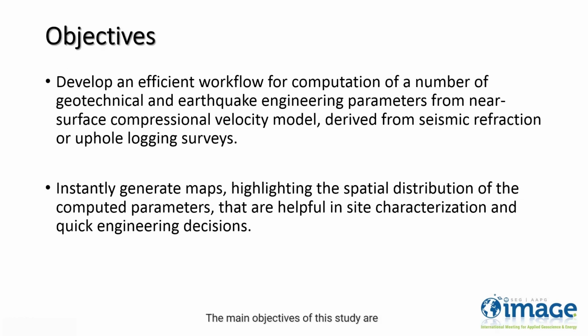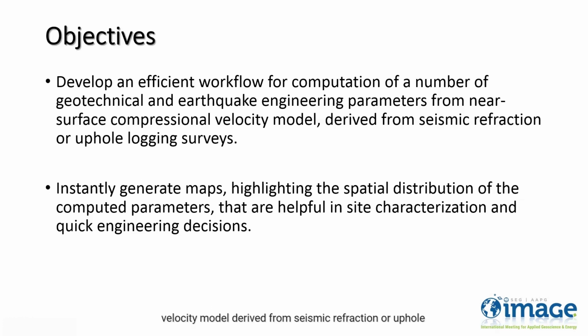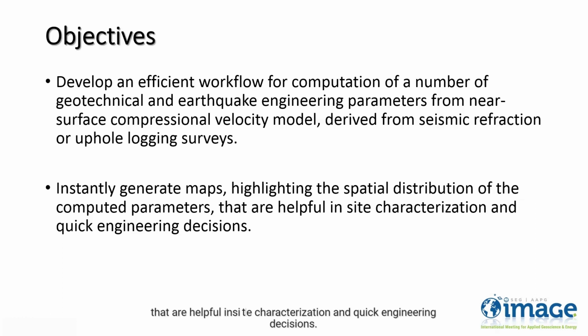The main objectives of this study are to develop an efficient workflow for computation of a number of geotechnical and earthquake engineering parameters from the near-surface compressional velocity model derived from seismic refraction or uphole logging surveys, and instantly generate maps highlighting the spatial distribution of the computed parameters that are helpful in site characterization and quick engineering decisions.